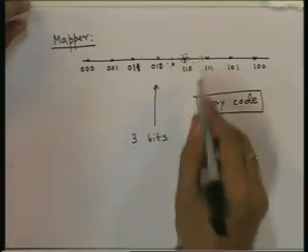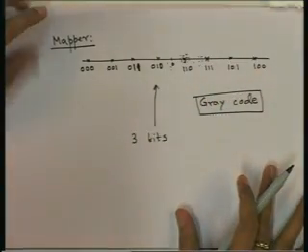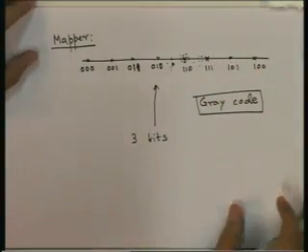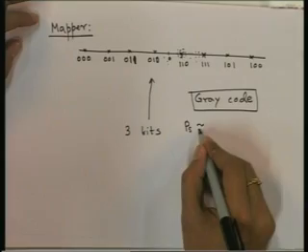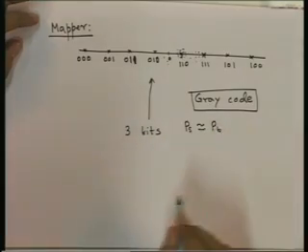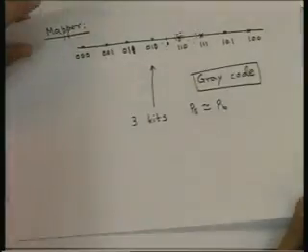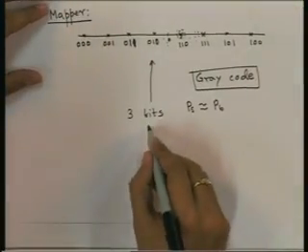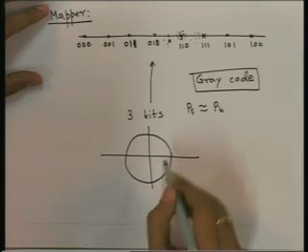So, as a result, in this case, if there is some error, most of the times one symbol error will result in 1 bit error. So, the probability of symbol error will be almost the same as the probability of bit error for this kind of mapping. Now, for PSK also a similar thing can be done, obviously, because there is some sequence in this.